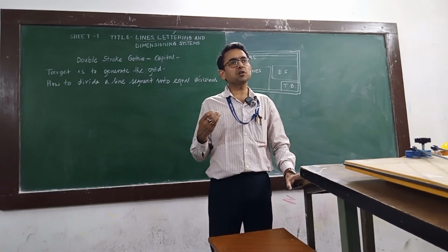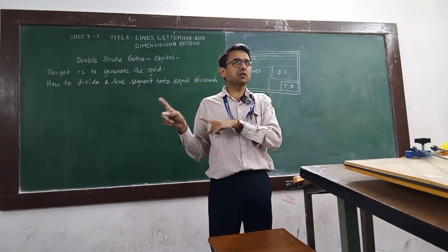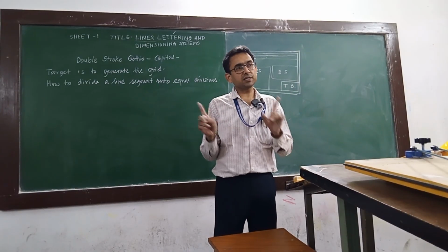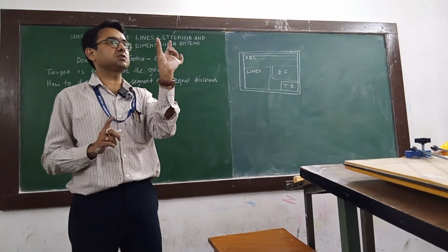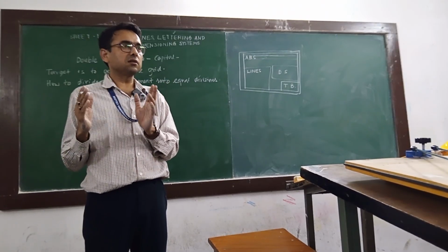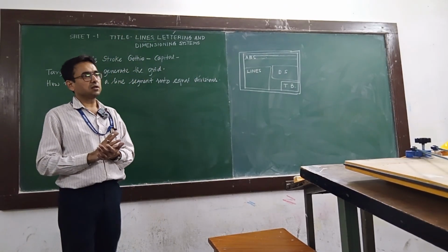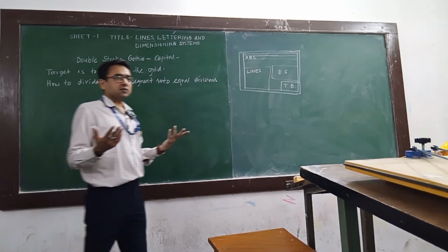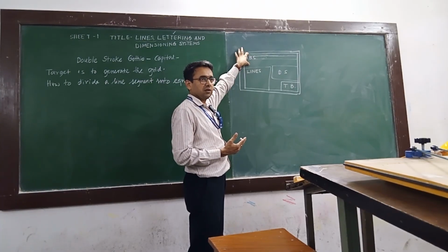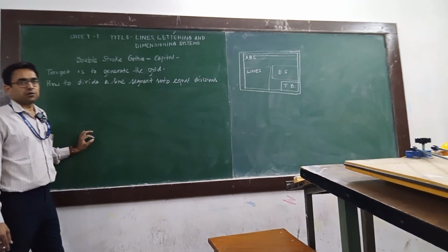So before starting the job, you have to plan how much drawing sheet is available, what drawings are required, and how and where to do them. Clear? So estimation is very important. You should have some idea of the dimensions and where to put them so that everything, text etc., fits along with the dimensions. That is the criterion of an engineer. Otherwise, if I started with a larger margin and cannot complete, it will be wasted. Okay, clear? So that should be done prior to starting, the estimation.